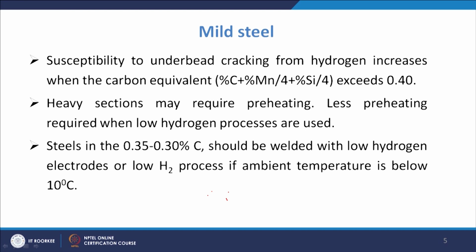hydrogen basically increases. Now, many a time the preheating requirement is mostly when you use the heavy sections. In that case you require the preheating, and less preheating will be required when you use the low hydrogen processes.